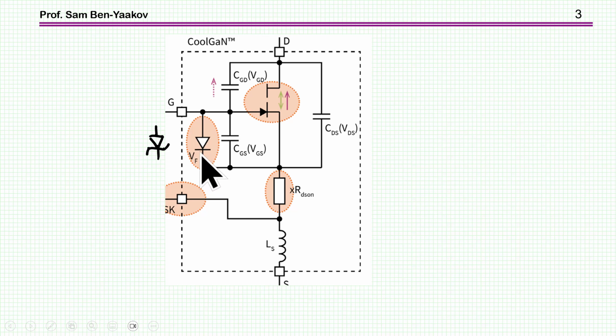In fact, this is not a diode. It is more like a Zener diode, because when the voltage is negative, if you pass a certain voltage, in the particular transistor we're going to talk about, it is 10 volt. So if you pass the minus 10 volt, then current will actually start flowing, the DC current. So it's more like a Zener diode.